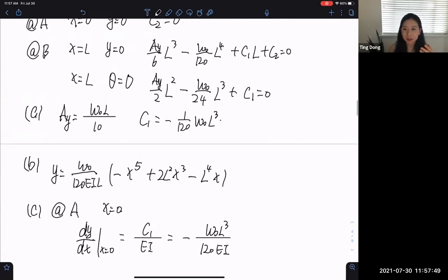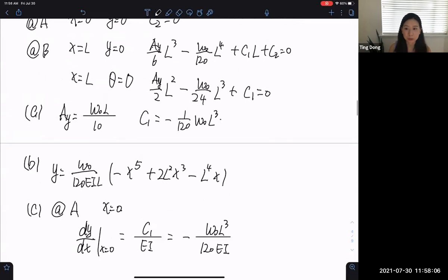We just have the bending moment equation, and once we get the equation of the slope, we integrate again and you get the equation for the deflection, and then we apply boundary conditions and we solve for all the unknowns. So the basic idea is the same. Probably the calculation part is a little bit complicated, but it's definitely doable. Any question here?